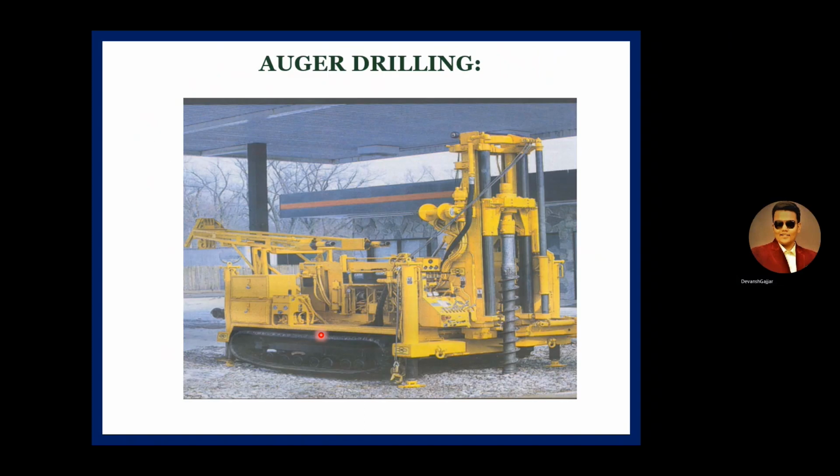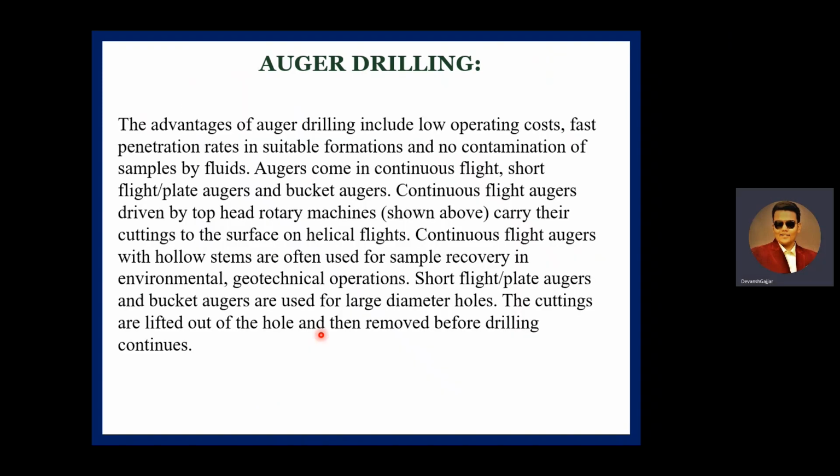Now, auger drilling. Auger drilling is not the most widely used in the oil and gas industry, but it is better to have an idea, because auger drilling is mostly used for wellbore pumps or in the construction of bridges, etc. The advantages of auger drilling include low operating cost, fast penetration rate in a suitable formation, and no contamination of samples by fluids.